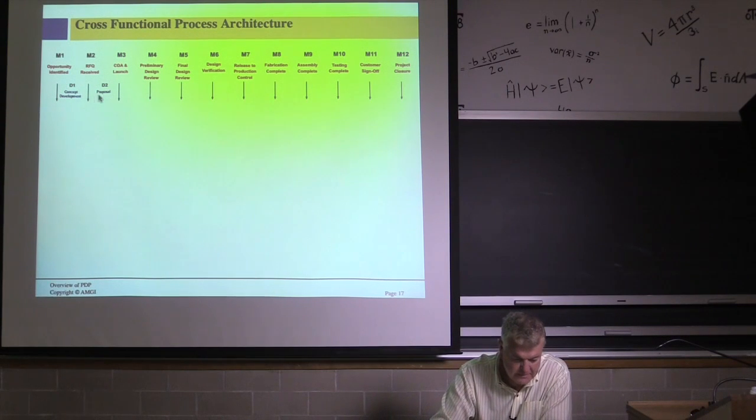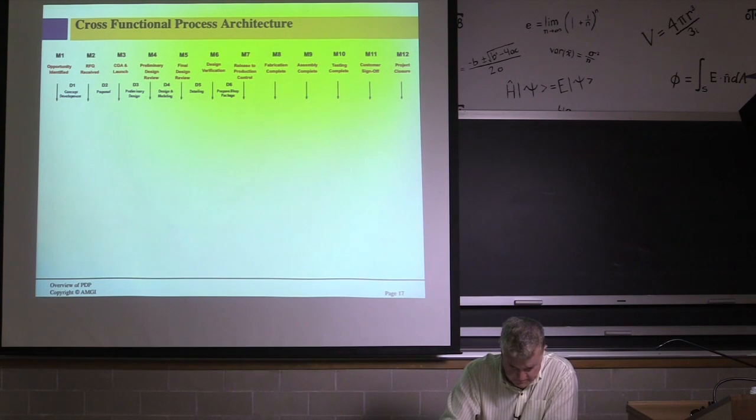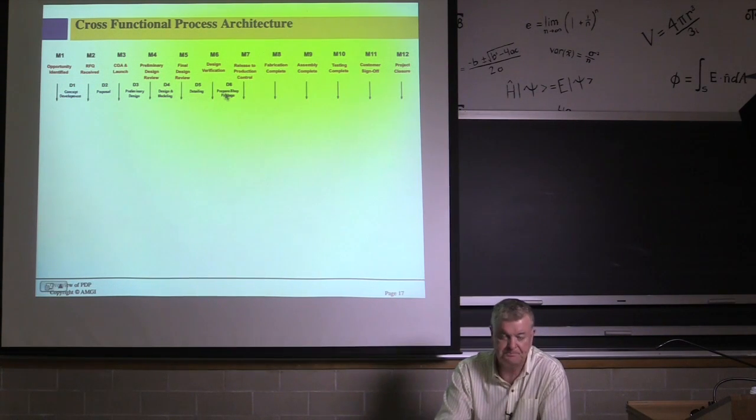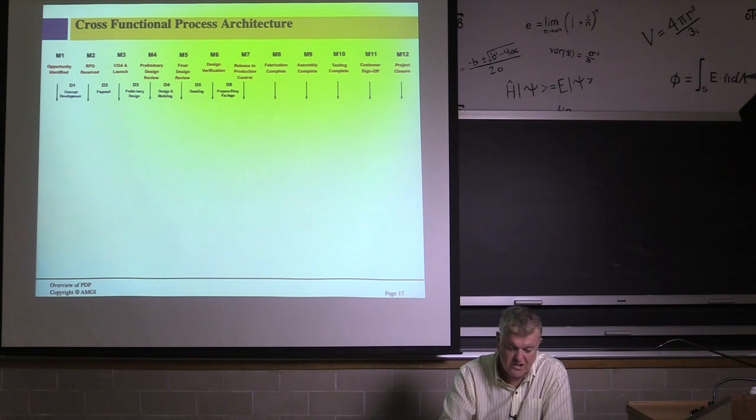So you have concept development, the proposal, preliminary design and modeling. We even made the change to that. This is detailed design of the specific parts that are then released to the shop for manufacture. Then you prepare a shop package. Shop package has got the drawings, it's got the writing, it's got the item information, it's got the assembly drawings and so on, and it's got a work order that you can book time to.